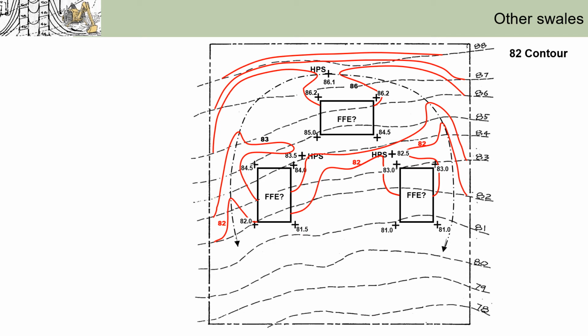Now, in order to find out where exactly the contours hit the building walls, basically you'd interpolate between the two building corners. For instance, for the building on the right, the two corners are 83 and 81, so 82 should hit the wall right in the middle. Okay, so interpolate between the two corners based on the green line distances.